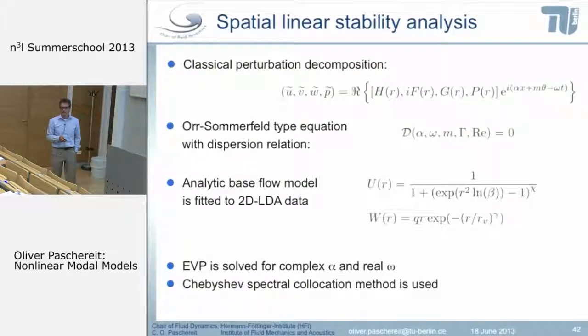And what we try then to apply on this decomposed flow field is a linear stability analysis. This linear stability analysis describes when a perturbation you put in the flow is unstable, this means grows, or is stable, this means it decays. And the basic principle, just to describe this very quickly, is that you perform this classical perturbation decomposition of your coherent velocity signals and pressure signal. And this is done in spatial direction, axial direction, and time direction, as well as in the mode, so in the azimuthal mode.